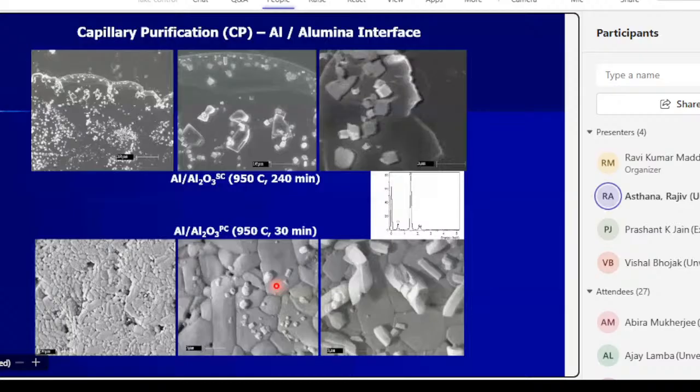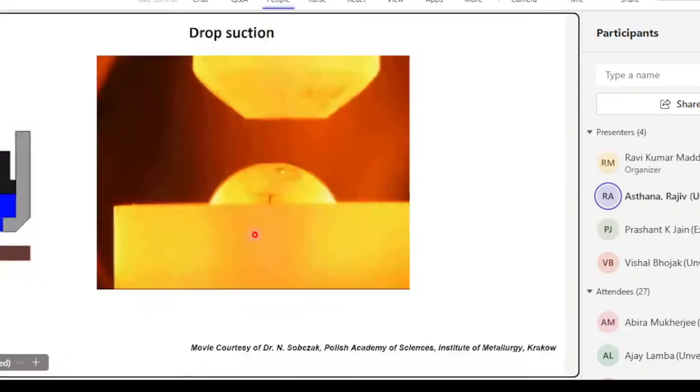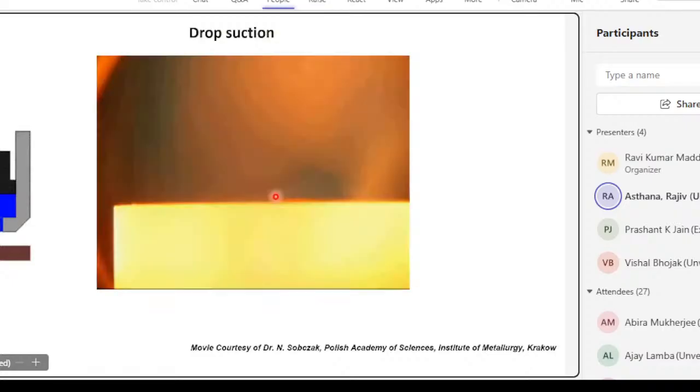So these are the AFM images of the liquid droplet side, and this is the side where you didn't have any liquid in contact with solid. These are different micrometer scales in the droplet. What we see is that even under 2 or 3 millimeter diameter droplets, you have little droplets that sit in dislocation edge pits.